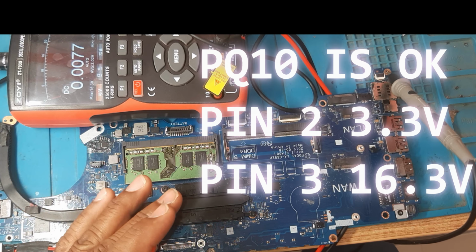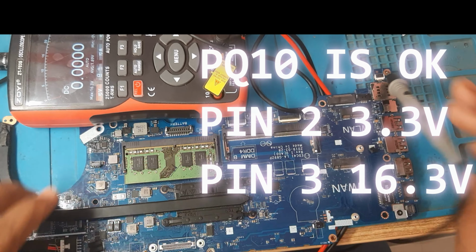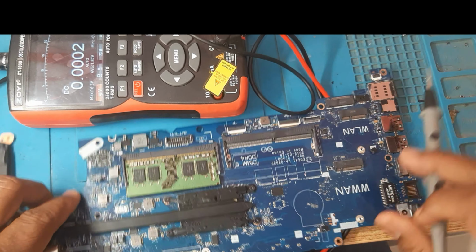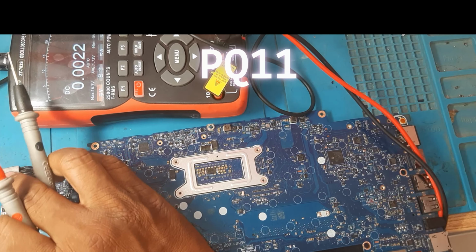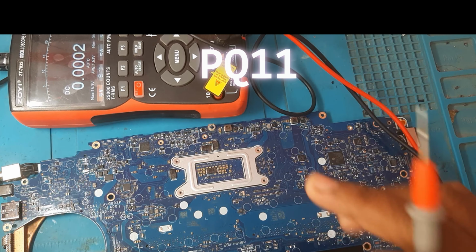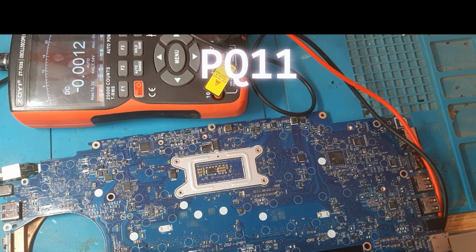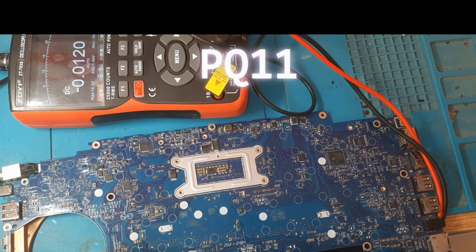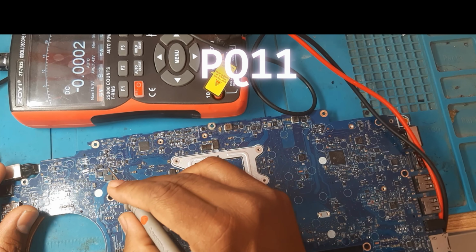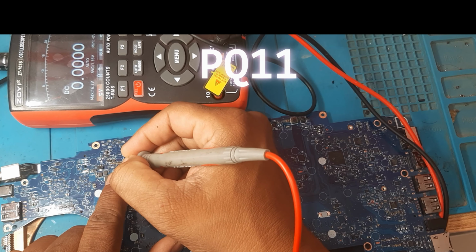Okay, if the voltage is good, then what about the P channel? That we need to check. The P channel PQ11, which I told you about now. Please check the schematic. While explaining the schematic, you will get bored, so that's why I am not explaining the schematic. Directly I am showing you the practical session. See, ground. PQ11. Okay, here is the gate, source, drain.